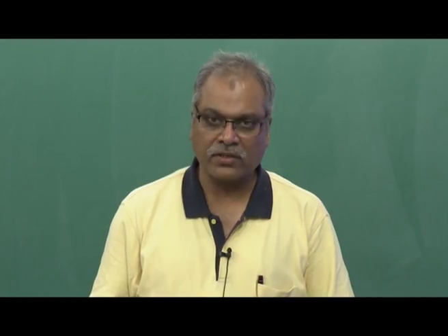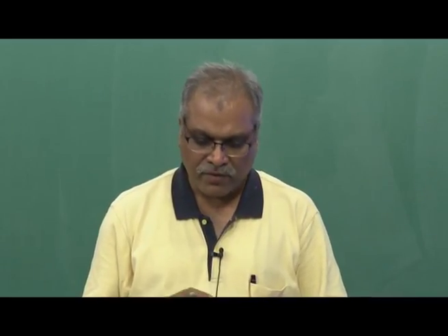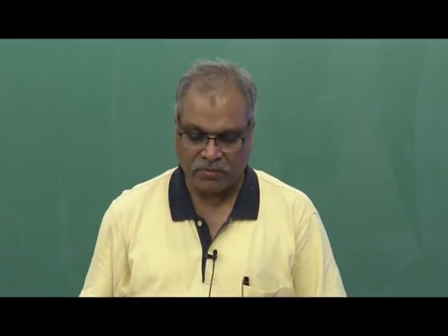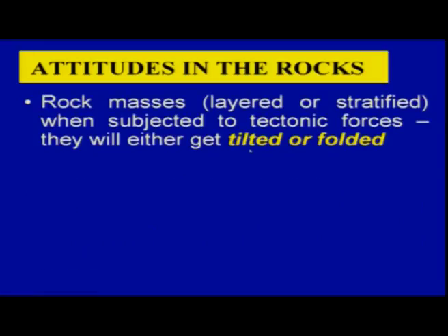Now, this is very important where we need to talk about the attitudes of the rocks. Each rock or sediment succession will have some attitudes. What are these attitudes? Mainly we deal with rocks that are tilted or folded. When the rocks are tilted or folded, we see these attitudes developed in the rocks. It is related to the direction in which they are oriented, how much they are tilted, the amount of tilt, and in which direction they are tilted. Those are termed the attitude.